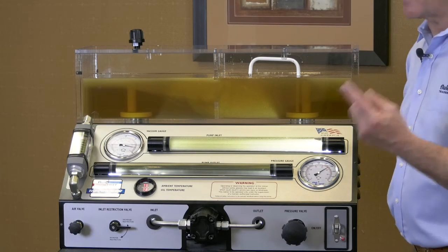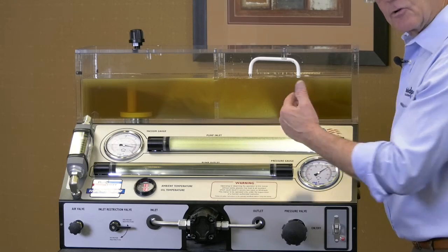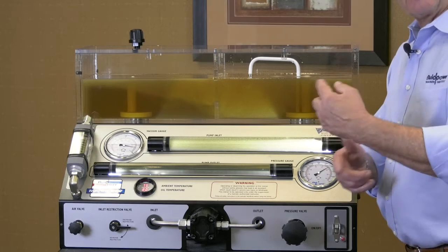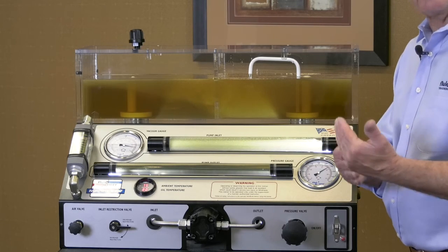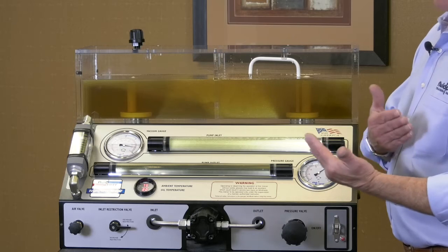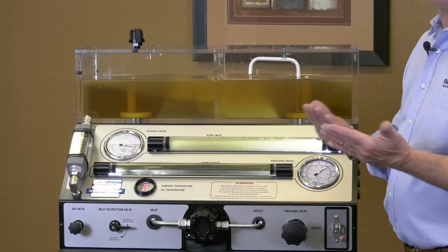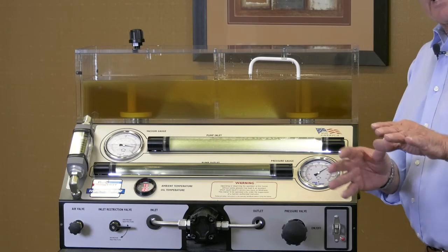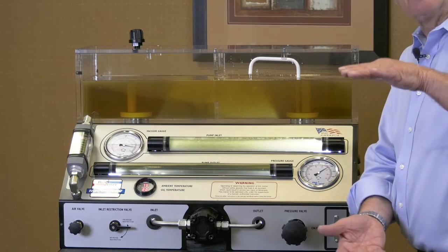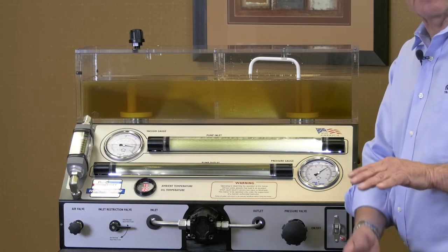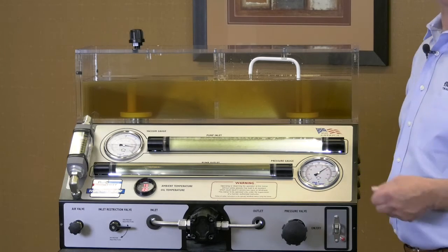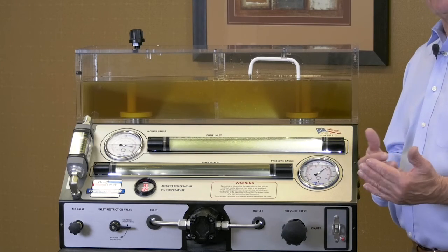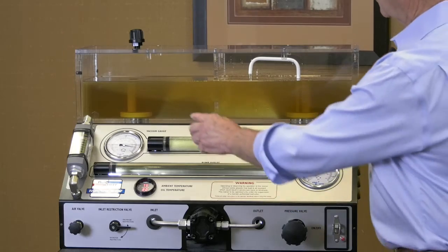Once again, you can see the immense amount of turbulence that is being generated by dropping the oil in on top of the oil. This is a very, very undesirable situation, and this comes from discharging any return line above the oil level. All return lines should terminate at least, by rule of thumb, 14 to 16 inches below the oil level. A very undesirable situation.